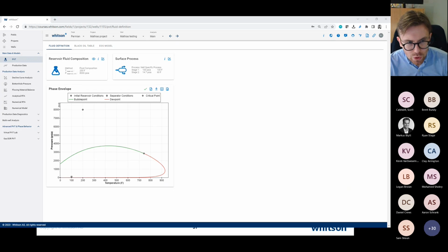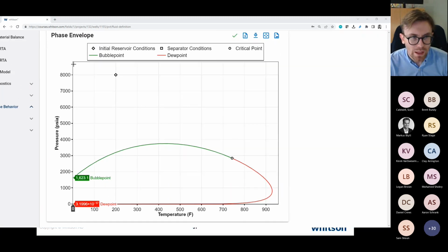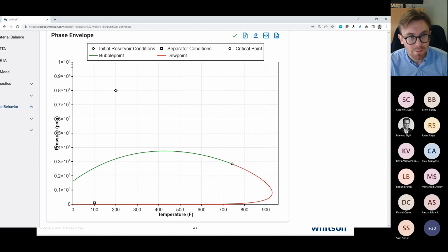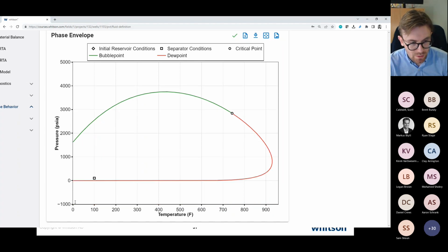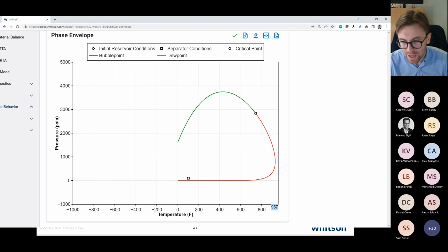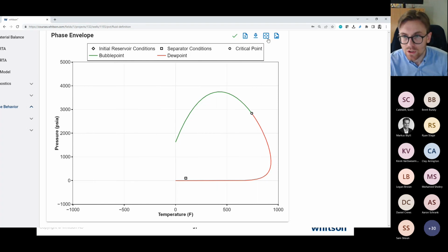So if you want to change the maximum part of the axis here, you need to go all the way up to the left of the plot or to the right of the plot here, depending on what axis you like to change. Or you can also do it down here if you like to. And you simply left click once, and you see this blue thing popping up, and then you can just type in the number 10,000, for instance. Or you can go down and make it 5,000 if you like to. So that goes also here. If I want to make this negative 1,000, you can do that here as well. So you have to be all the way to the end to be able to make these changes.